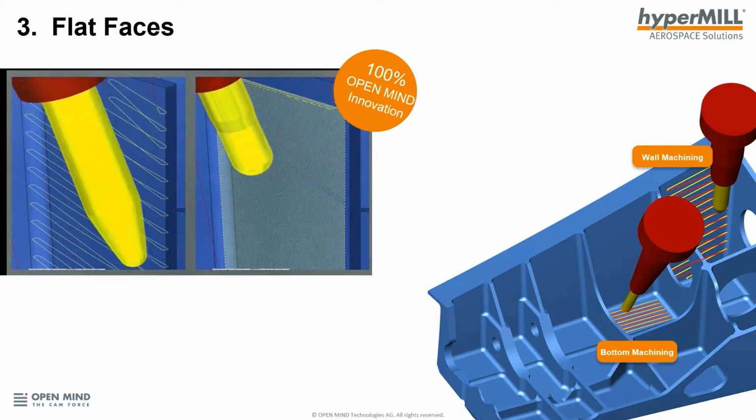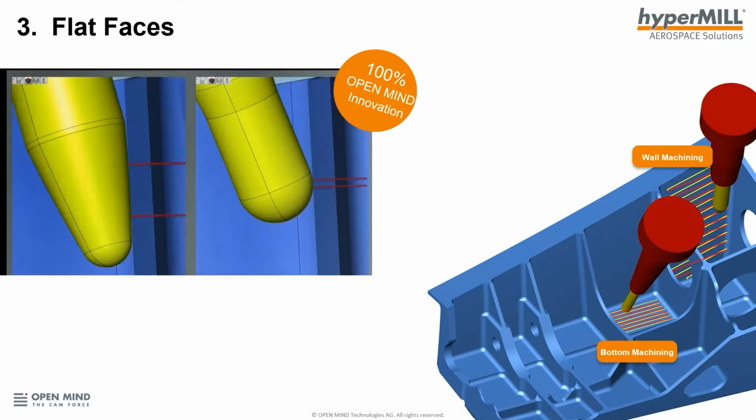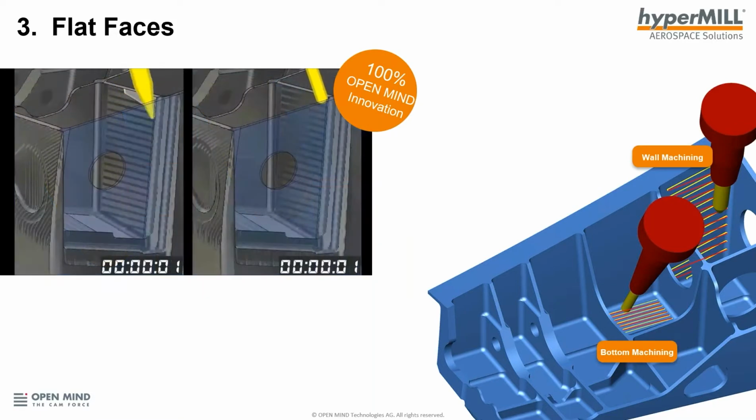So the video shows, on the far left-hand side, the barrel tool. This is quite a large radius, and you can see it moving in this pocket, using a simultaneous motion to get right into the corner. As it comes across the face, it pendulums so that we're getting the tool right into that corner.